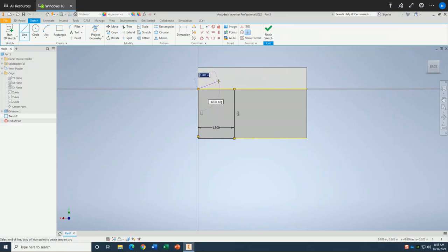I'm going to press the tab key so that it's highlighted. Again, I'm not missing the vision of the footprint line with the center point. I'm typing 120. This is quite a challenge. Enter, and then click on the second line. And escape key. So this is the one dormer that I'd like to keep, and the angles are perfect, and the lengths of the lines are perfect.